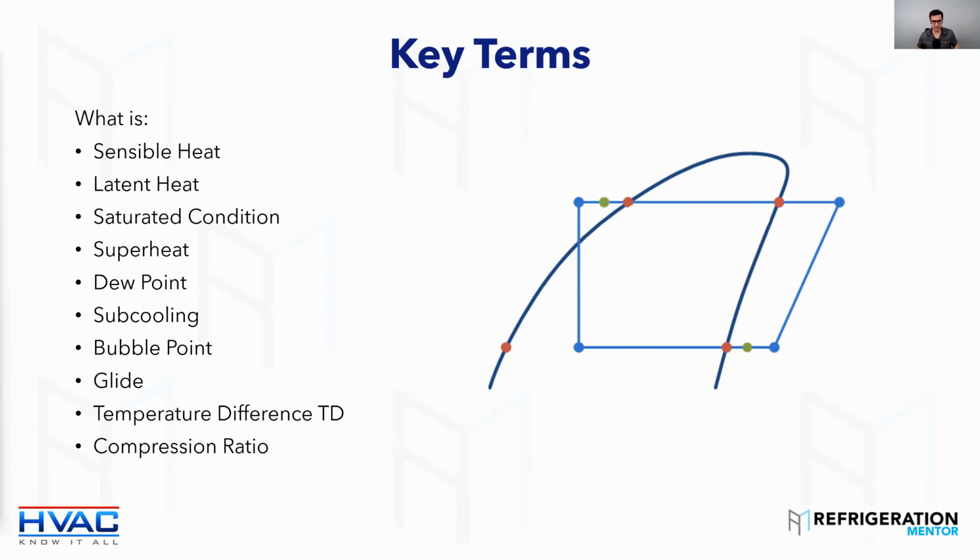Yeah, broken valves, great. This is what happens with a lot of units when you're trying to pump them down, you're holding in the contactor and all of a sudden it just stops. Scrolls aren't meant to be pumped down. Refrigeration scrolls, well, Copeland anyway, are designed for a 26:1 compression ratio. So it gets up to say 25, 26, and when you get over that, it's going to separate, because it unbalances the floating seal.